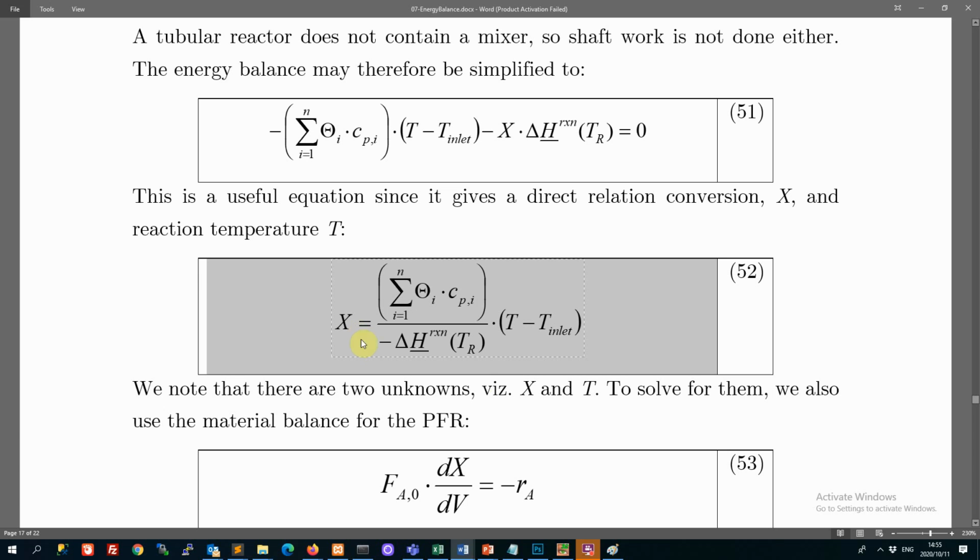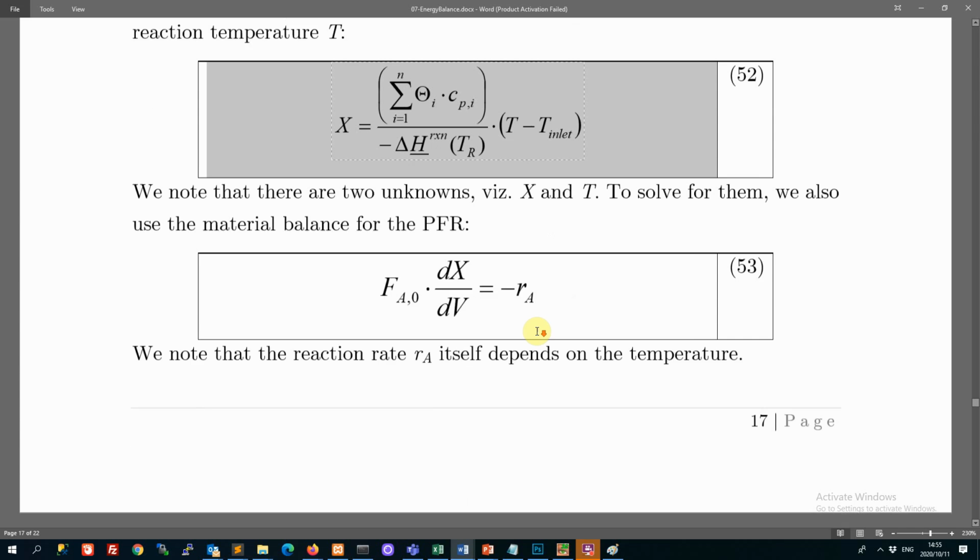So even if you have a reactor with lots of heat transfer going on, it's always useful to think about the adiabatic relationship, to simulate it, play around with temperatures, and see how the conversion responds. That gives you a good indication about the tendency of that reaction to respond to temperature. So I like to think of this as a general expression. Anyway,